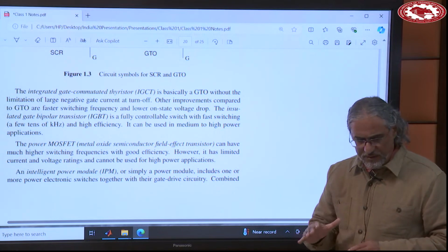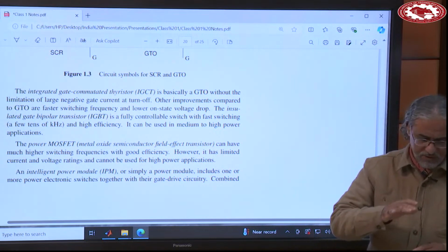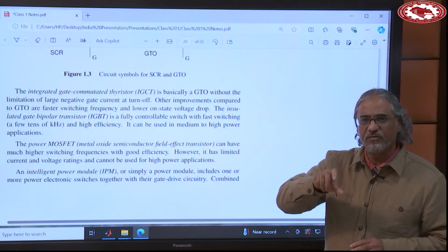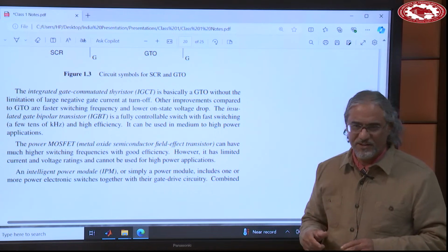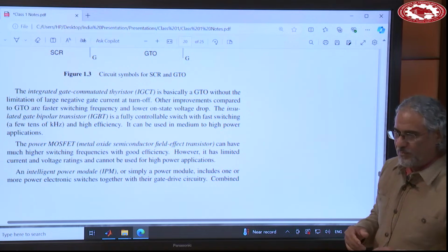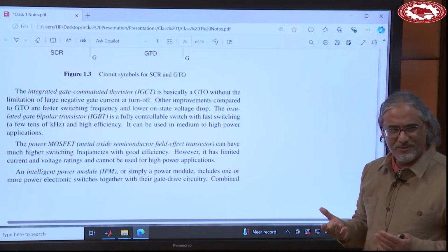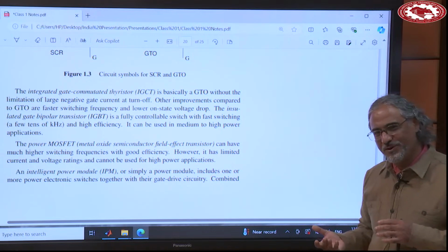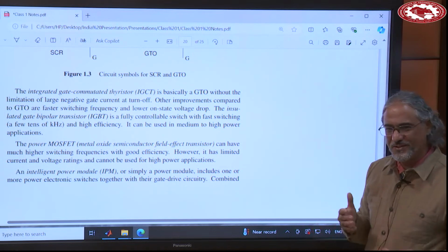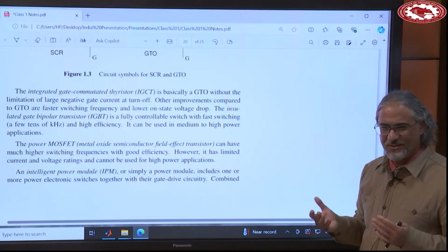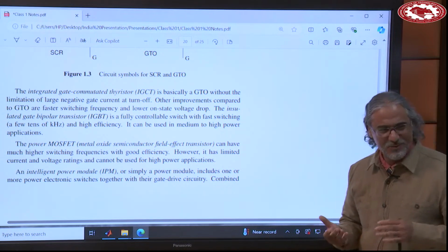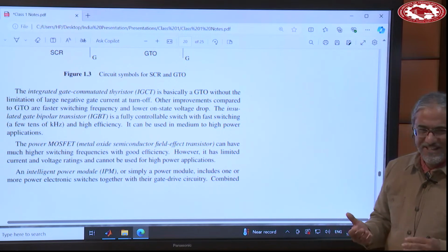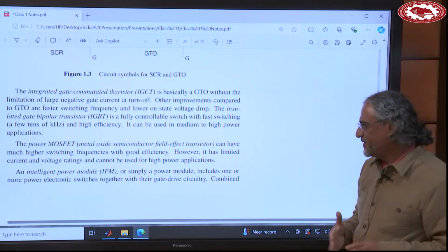For the voltage, when it is on there is only a small voltage across it, but when it is off, the question is how much maximum voltage it can tolerate. So power does not really mean a lot in a power electronic switch. But some people like to multiply these two entities, this voltage and that current, which is not really scientific, because one of them is for the on state and one is for the off state. And they call it the power rating of the switch.